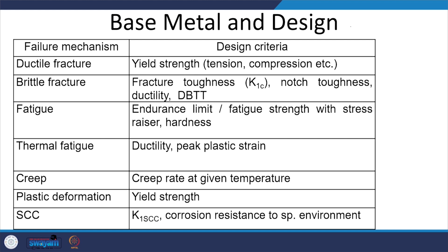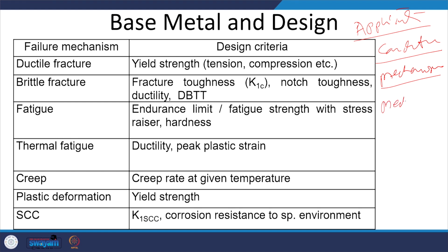So, let us see it in this way. See, the weld joint will be used for certain applications. Application means there will be certain working conditions. In those working conditions, the joint will have the failure tendency to fail by certain mechanisms, and for resisting the failure of the weld joint by those mechanisms, material should have certain set of mechanical or chemical properties. Okay. So, we need to develop the joint in such a way that we use suitable filler or electrode in such a way that it offers you the desired set of properties.